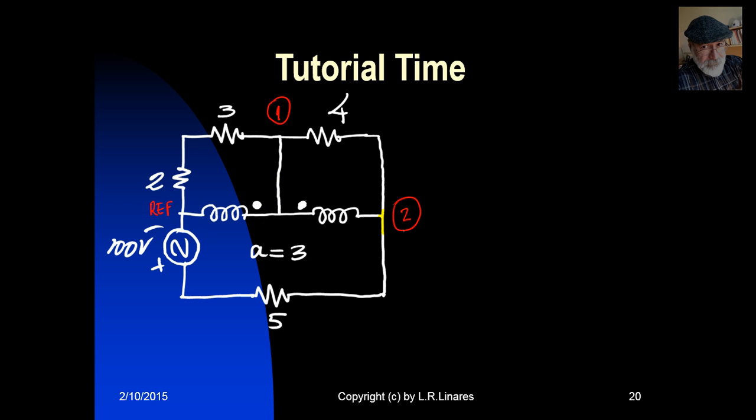Nothing new. However, choosing my nodes like that, immediately we say the voltage applied to the primary on the left side is just V1, right? So let me draw it here. This voltage is V1, the voltage in the primary. Well, immediately I know that the voltage in the secondary will have this polarity. What else? We know that the voltage in the secondary is going to be 1/3 of the voltage in the primary, and I write that V1 divided by 3.